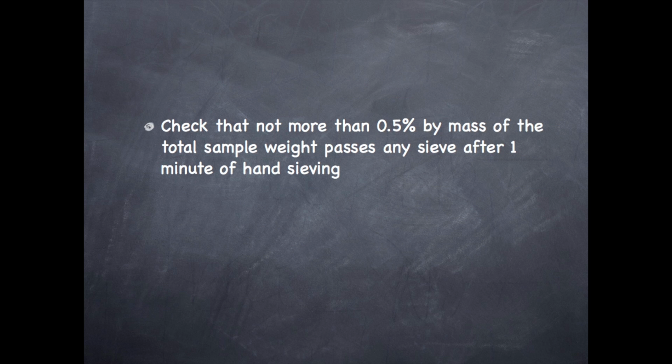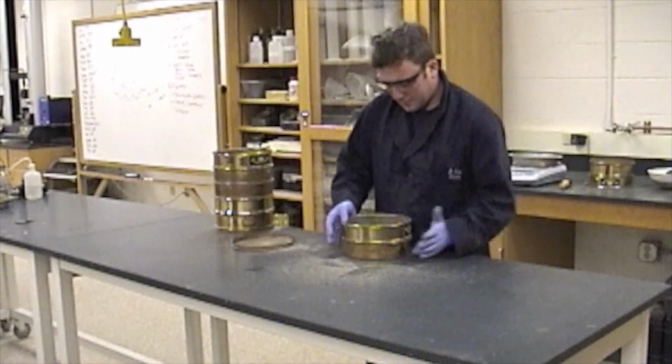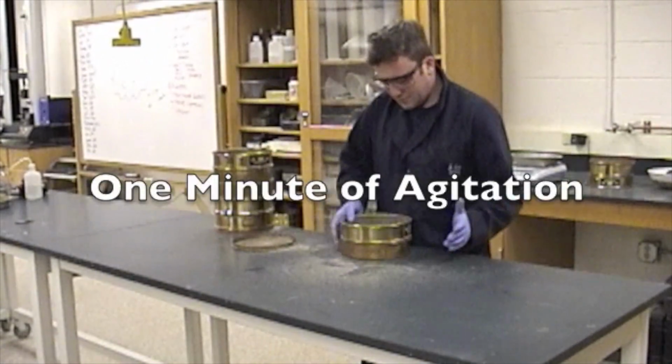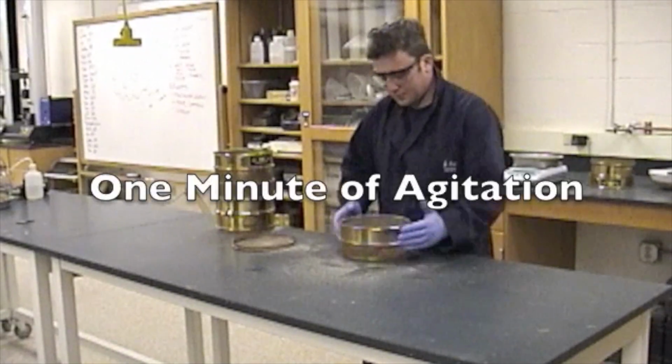But before we do any calculations, we want to ensure that we have actually sieved this material for a sufficient amount of time. We do this by checking that not more than 0.5% by mass of the total sample weight passes any given sieve after 1 minute of hand sieving. So we do this by selecting a sieve and putting it snugly into the pan and then tapping the sides of those sieves about 150 times per minute, turning the sieves about 1/6 of a turn every 25 taps.